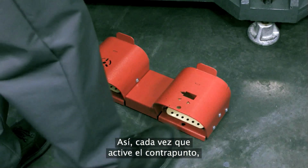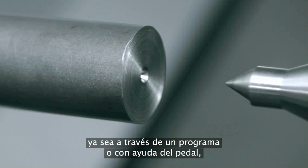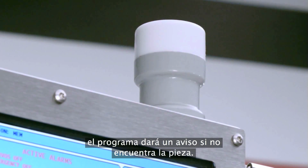That way, anytime the tailstock is activated, whether by a program or with the foot pedal, it will fault out if it doesn't find a part.